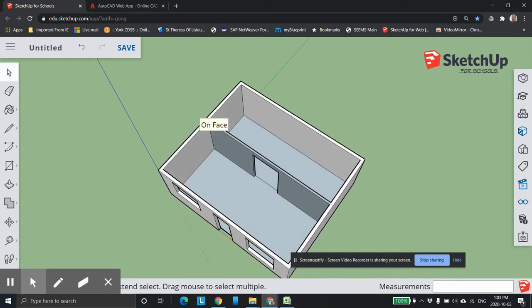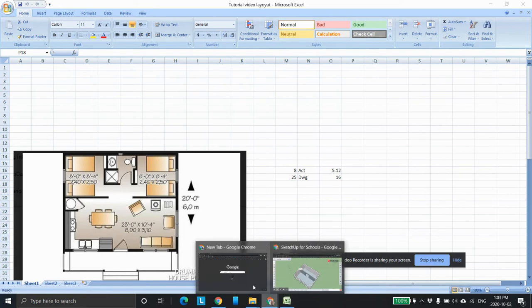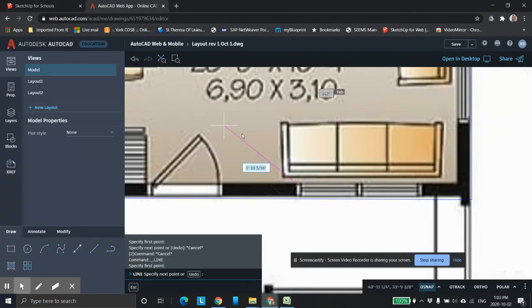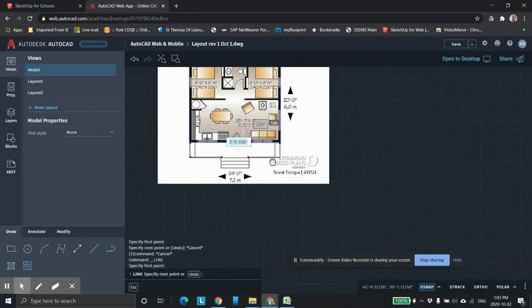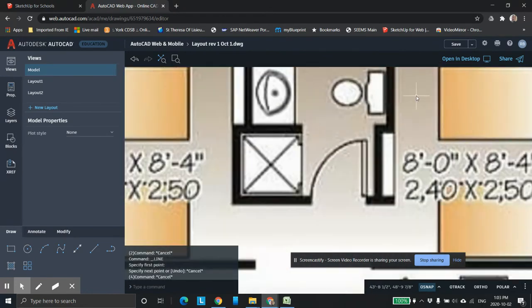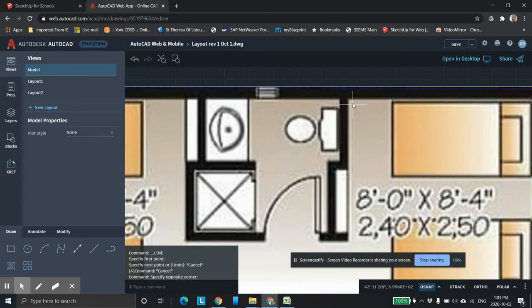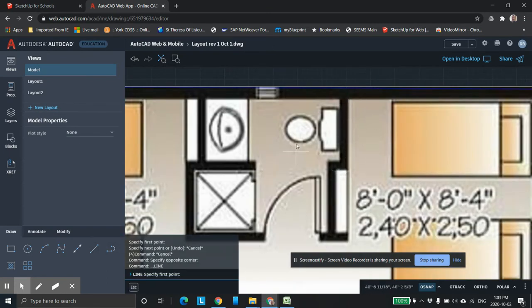So you're going to come in here and start drawing these. That's what I was trying to say. So you're going to come in here and accurately go into AutoCAD. We're going to hit the escape key, and I want to first draw this one down here. I want to go from there down to here. So I can get the line tool. I can go right in the corner nicely, like so.